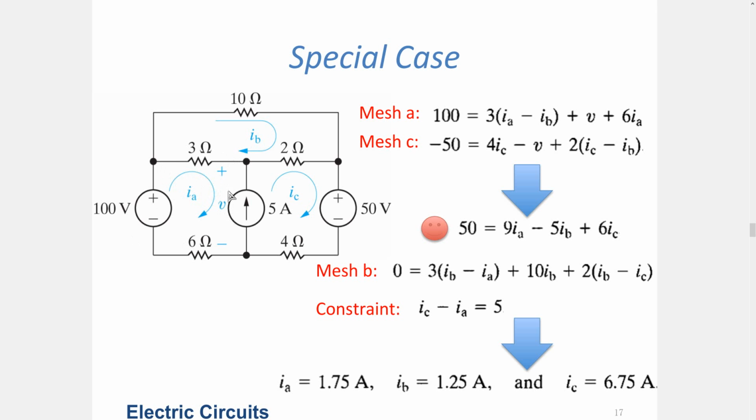Then rotating this, I have some V which is unknown because we don't know the voltage of the current source and we don't know the currents of the voltage sources. So this will be solved in the last step. So I have to take it as it is. Since I am rotating in the same direction, I will write a positive V because I'm supposing that IA is flowing in this direction and the voltage drop is defined like this, but arbitrarily, okay? And since it's the same direction, I take it as a positive value.